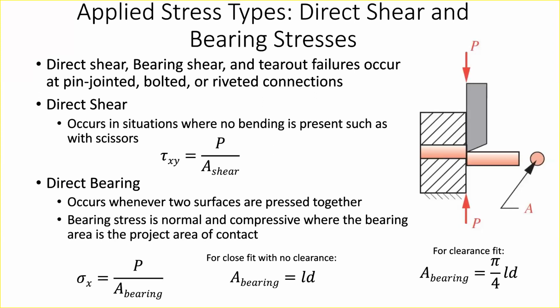So as you're thinking about how you connect parts, how you design your parts, try to recognize these patterns of loading. Ask yourself, in this region of the part, am I dealing with shear loads? Am I dealing with bending loads? And then start asking yourself, how can I constrain this part differently so that even if I'm supporting the same load, I change the loading within the part to make it more optimal?